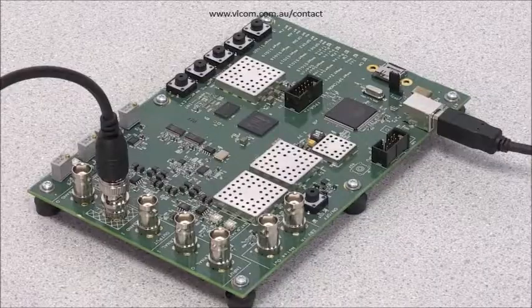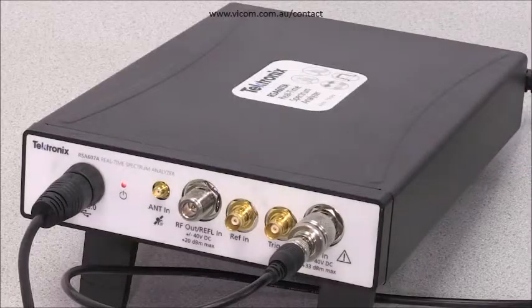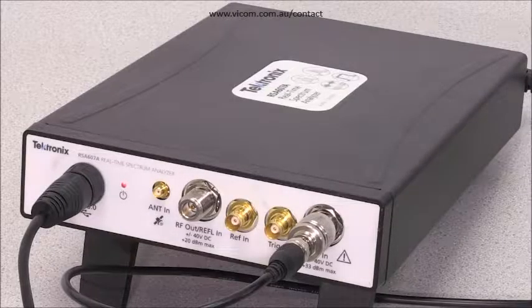I'd like to show you a quick how-to video for doing Bluetooth pre-compliance checks on a Bluetooth device. In this case, I've got a demo board here available, and I'm going to do the test with this RSA 607A real-time spectrum analyzer. It's a USB analyzer that's connected to my PC. The PC will be running SignalVu-PC software to control the analyzer.